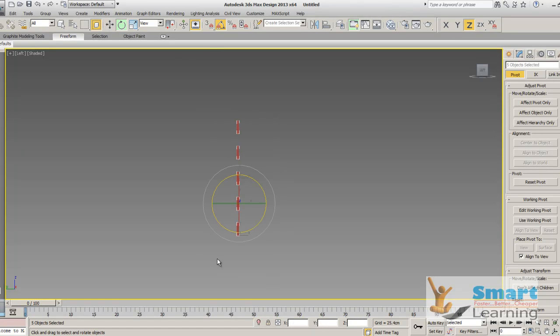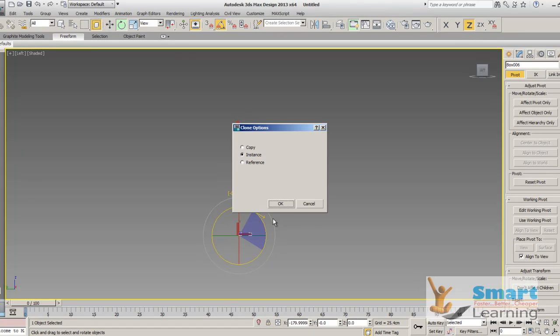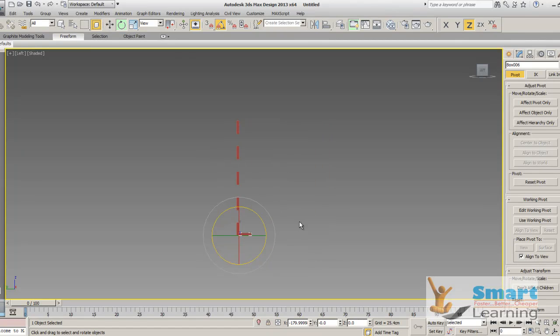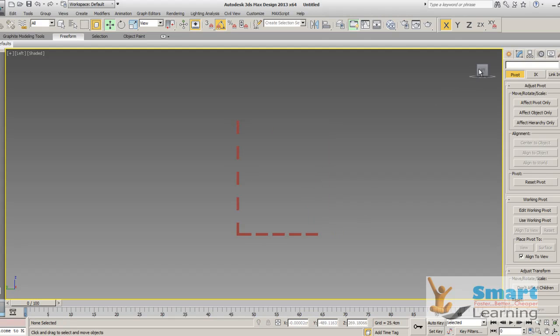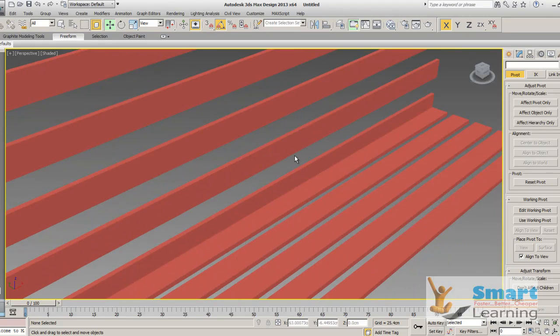I'll select the objects or a particular object and go to shift, and you can get the 90 orientation. Then I'll go to my move handle, and you can now place it with a requisite number, maybe 4, and now I can see the preview how it looks like.